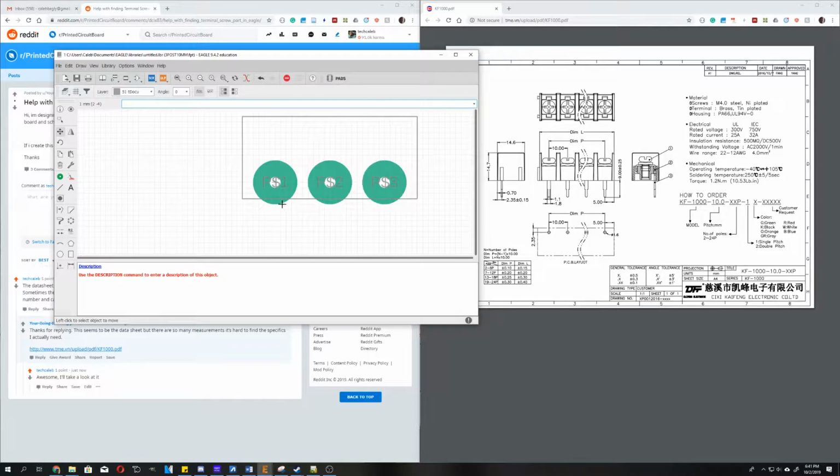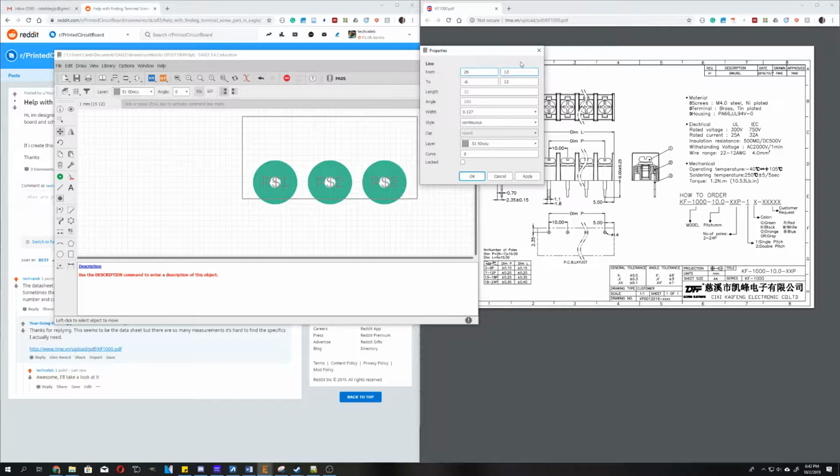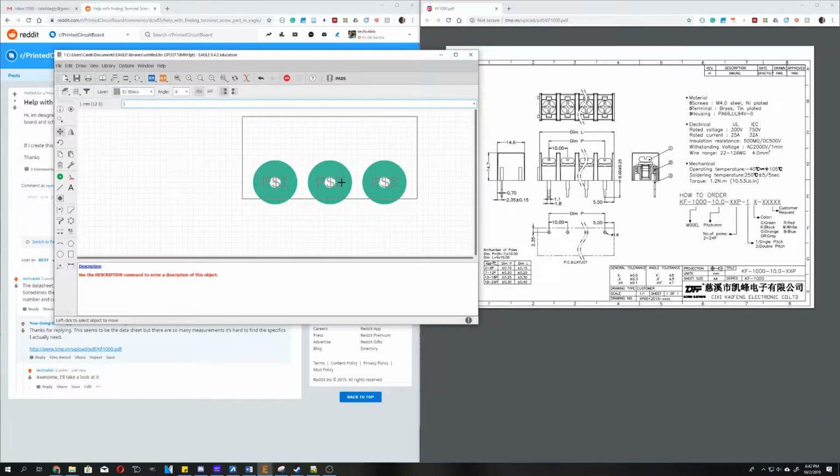So we know that these might stick out a little bit under the side, which you might want to reduce the diameter if that matters to you. Who knows? But then the last dimension we need is the width here, which is 14.6. And so if this is -3 and we're adding 14.6, let's say 15, again, round that up to a slightly wider value. Let's say 15 minus 3, that'd be 12. So we would want this one to go all the way up to 12. And indeed, that's exactly, I drew it almost right in place. Sure enough, right off the bat. Okay, so that right there, very simple layout.